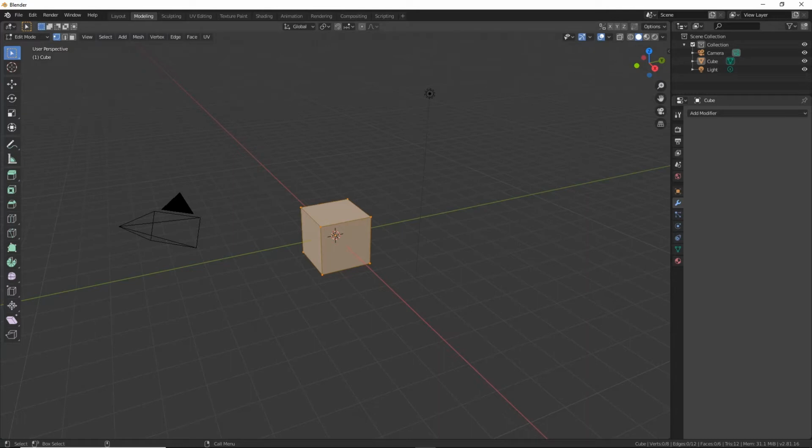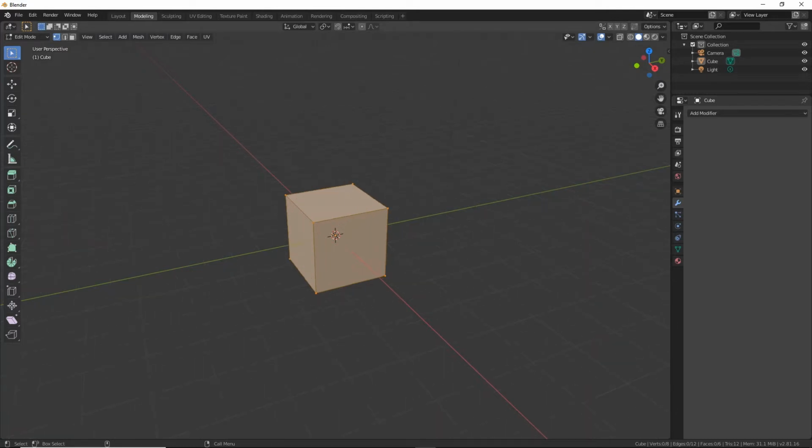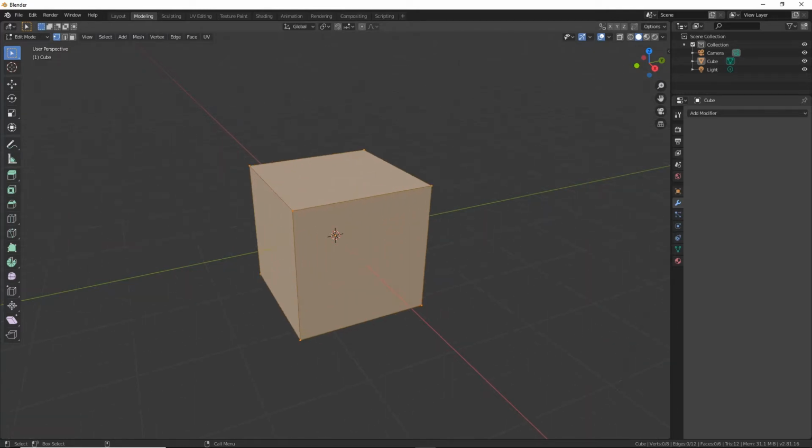But modeling for the moment, because if we just zoom in now, just use my middle mouse wheel, you'll see that every corner of our box or cube has dots on it. And I can click on these dots like that. Now these are vertices, and they mark out the outside points of every polygon. Now in between those we have these edges.